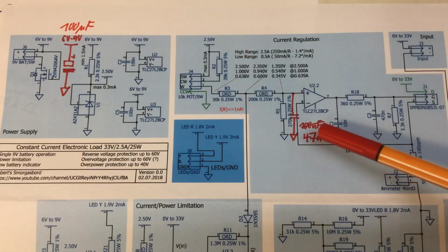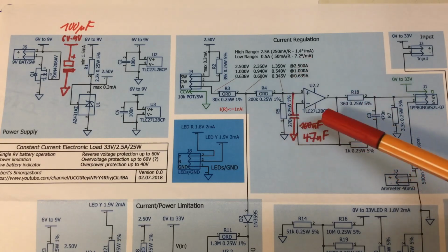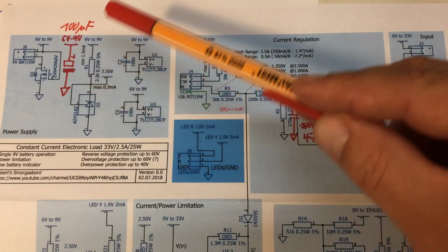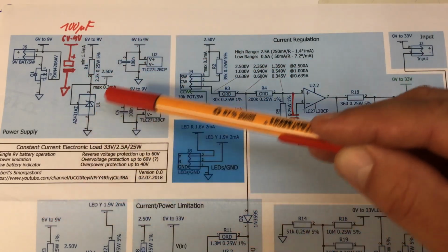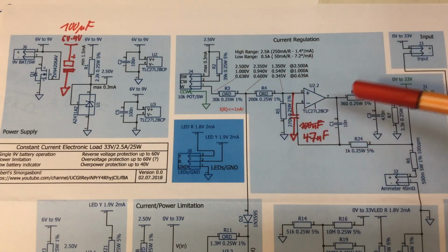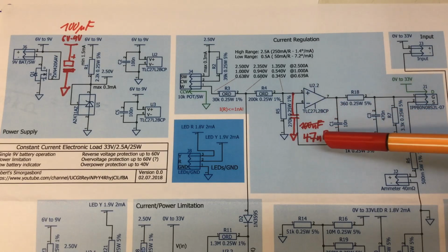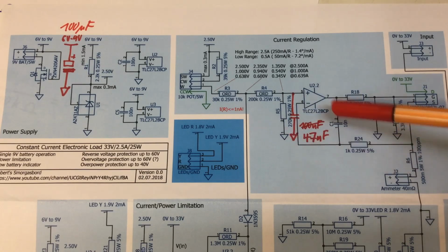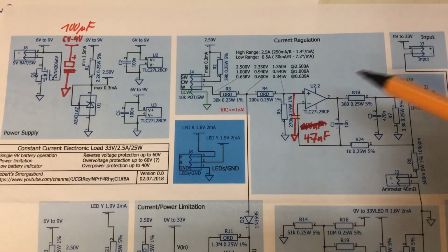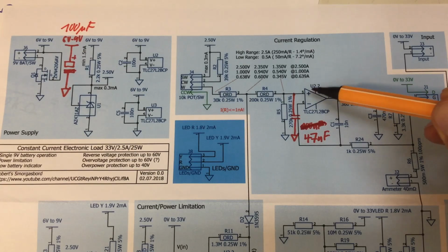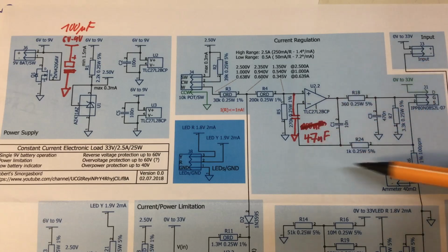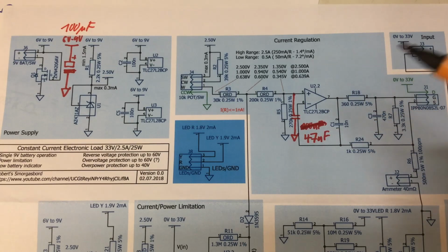And we reduced that, and we went up to 100 nanofarads in conjunction with that, because our power rail was now ramping up really nicely, but there were still some oscillations here, and we went back down to 47 nanofarads. That is obviously enough to filter that input, to keep that stable, protected from any spikes which mess up our current regulation.